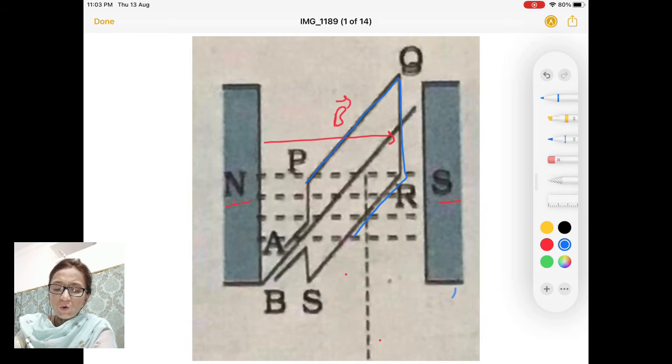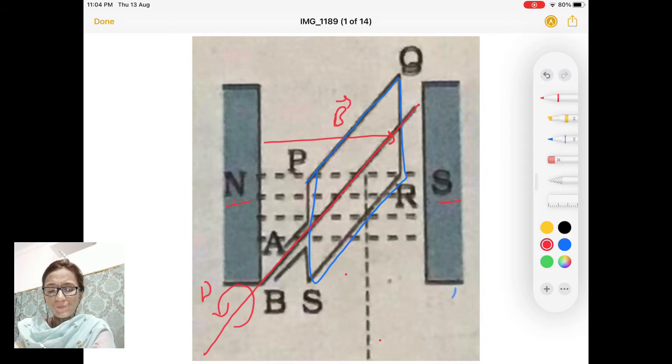Then you have a rectangular coil placed in between these two pole pieces. This coil is fixed over an axle. Now this axle is rotated with uniform angular velocity omega by some external source of mechanical energy. So in a hydropower plant, this axle is rotated with the help of running water. In a thermal power plant, whereas, it is rotated by the steam of water.